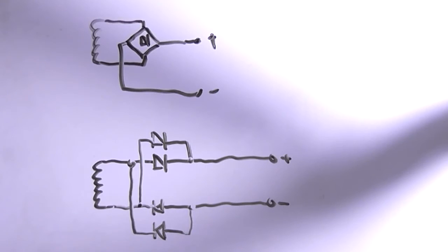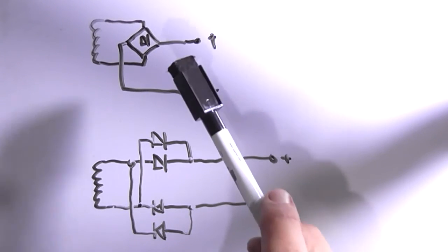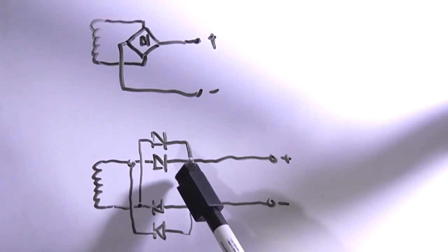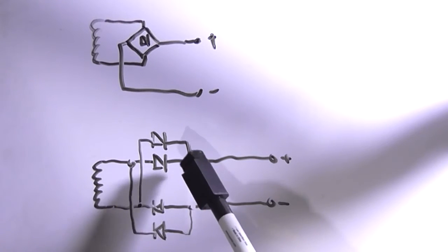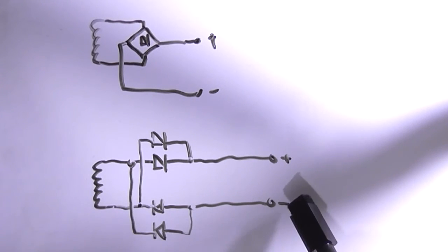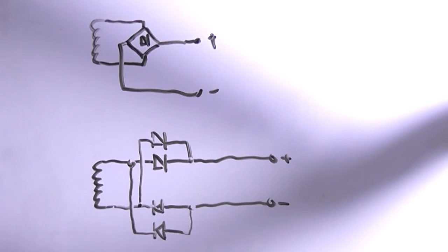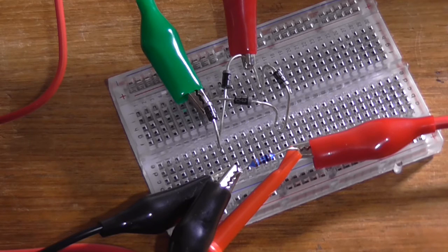correct capacitor. And before we continue on that, you'll often see the full bridge rectifier represented on a schematic as either just a diamond with a diode symbol in the middle of it, to save drawing all the diodes, or you may see it drawn like this with the two cathodes on one side joined together forming positive, two anodes on the other forming the negative, and then each crossing over to the other winding of the transformer respectively to fill in the bridge. But it all represents the same thing at the end of the day. Full bridge rectifier. And welcome to the full bridge rectifier.